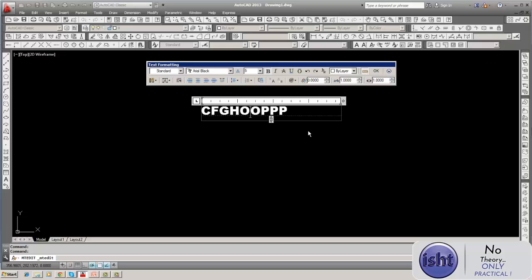So what we have to do is, we first fix the scale factor. See the drawing size, what scale factor you are going to apply, you decide. After deciding the scale factor, you have to select the scale factor for the letters. Suppose you want letters to appear as 5 mm size in the actual drawing sheet.